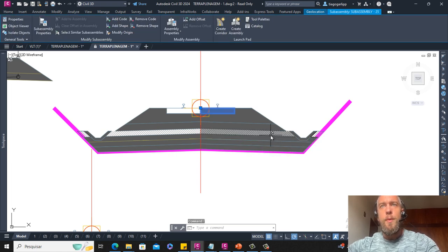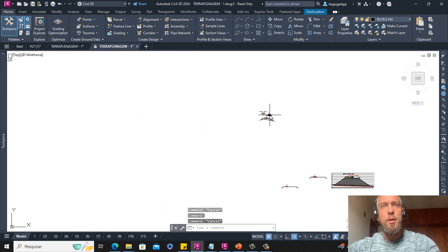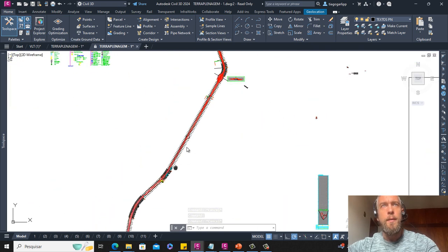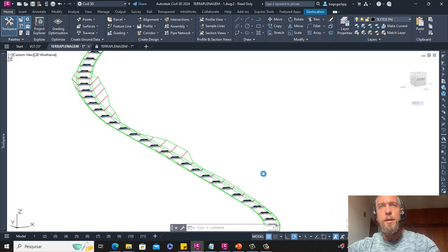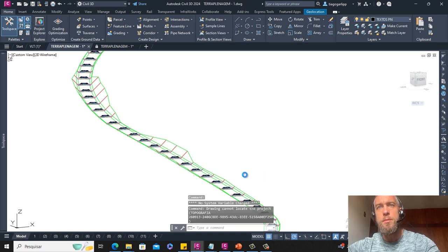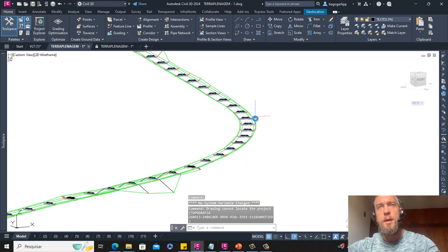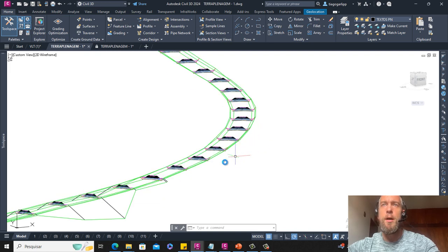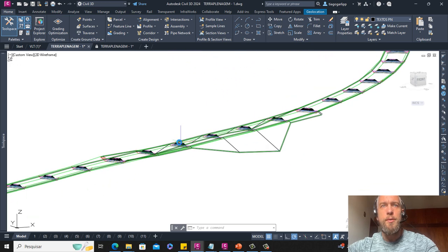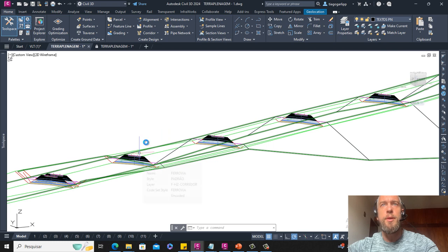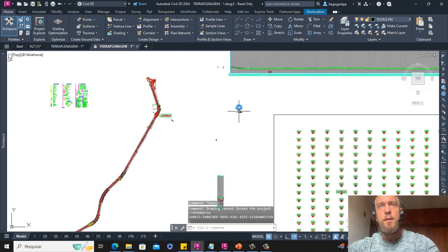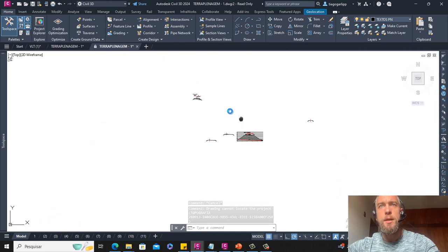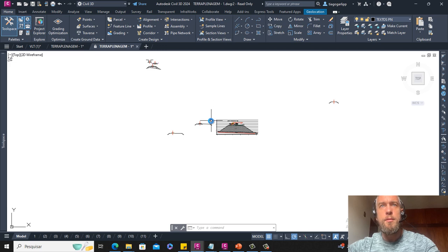When we go directly to the corridor, we have a switch for this drawing. We have the multiple typical sections, the multiple assemblies along the whole of the corridor. So to create this, we created three assemblies and sub-assemblies, three different kinds of sub-assemblies regarding the embankment.